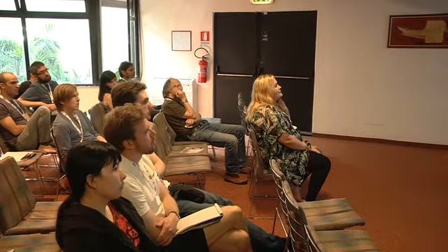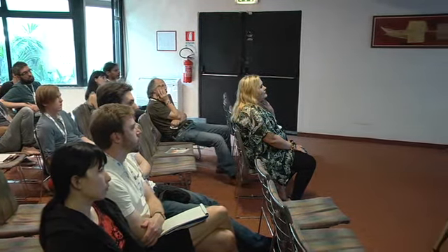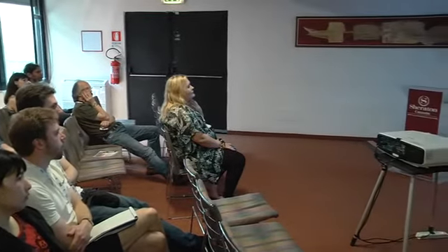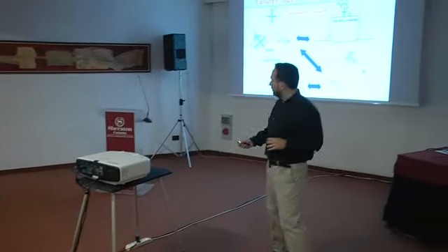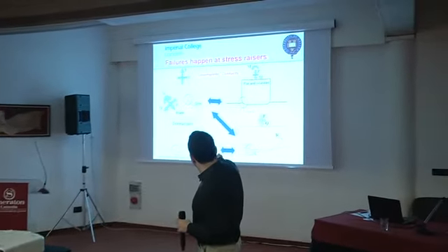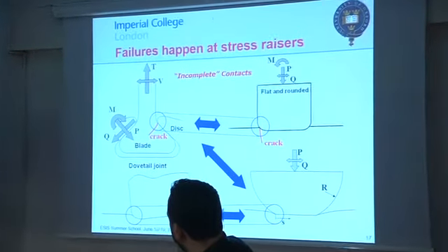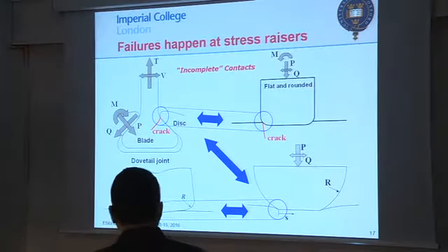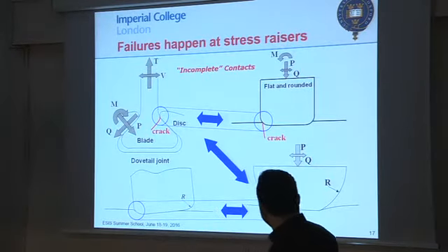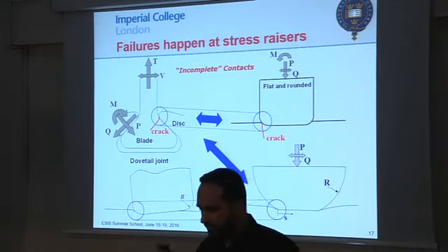You will see it later, but in reality, it's all about modulating these loads and these loads, or these loads, so that you can replicate the state of stress there. The idea is that you need to come up with a way to modify, say, these loads to obtain the same state of stress that you get from the load on the blade when it runs in an engine. The idea is that you will need to scale those so that the state of stress there is the same as the state of stress there. And that's how you do it.